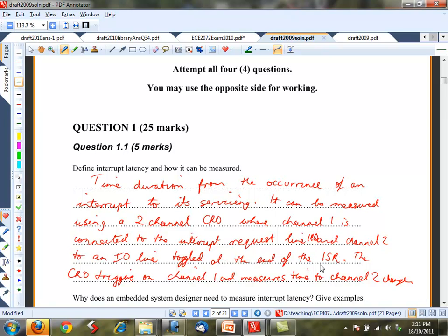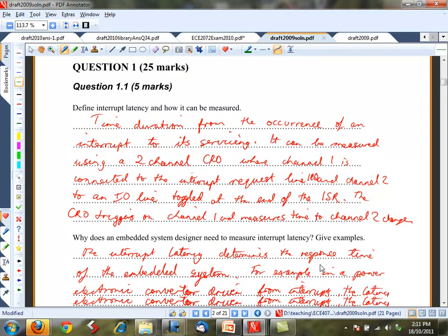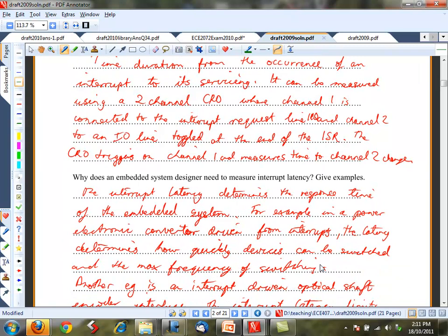Now, you might ask, well, could you do this with other mechanisms? Could you do it in a software sense? And the answer is no, you can't reliably do that because of the way the interrupts are structured in the real-time kernel. So you only have a 1 millisecond resolution of the interrupts typically, and here we really need this down to microsecond type precision. So that's why you normally do it in a hardware measurement.